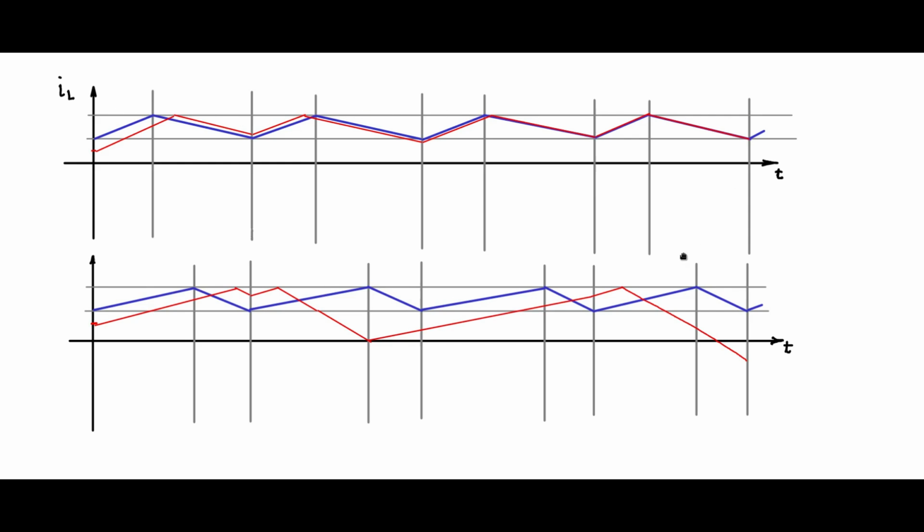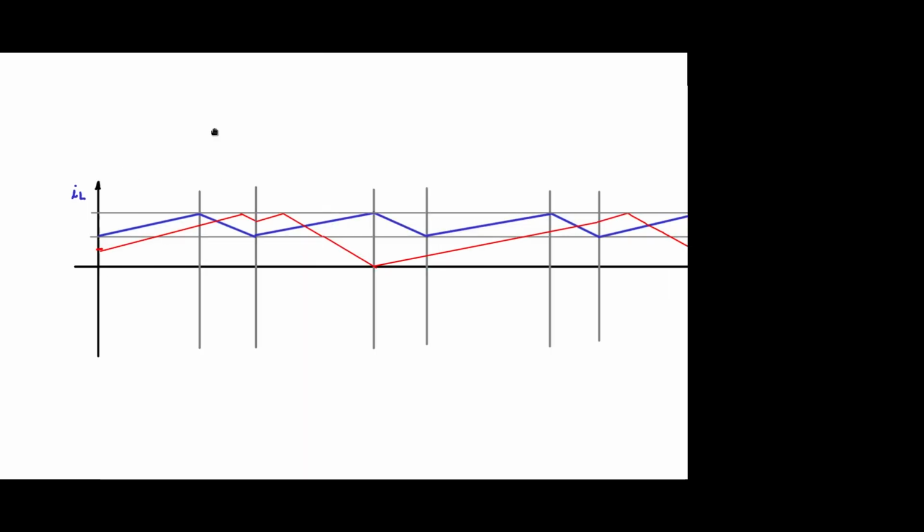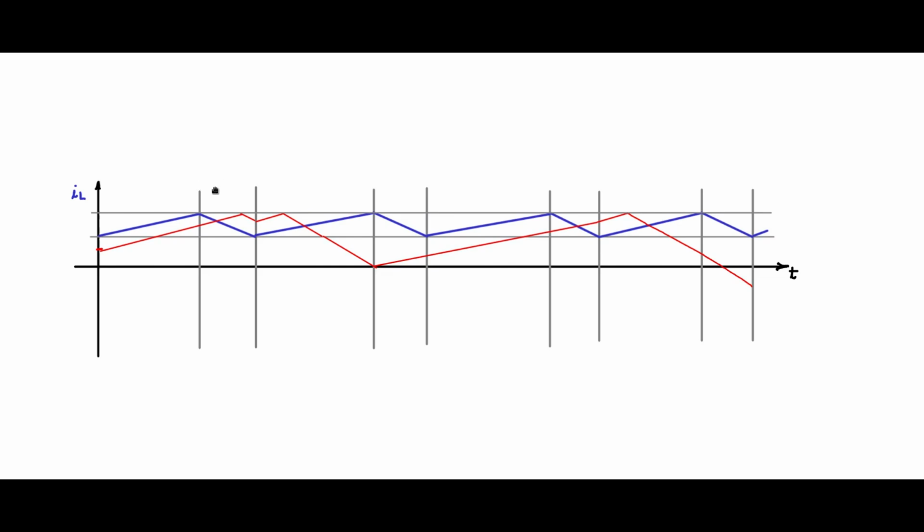How do we solve this problem? Let us seek a solution and try to find out how to do that and implement that. Let me consider the problem case waveform. Here the duty cycle is greater than 0.5, and we see that if we give a disturbance, the disturbance keeps growing and leads to an unstable inductor current waveform.